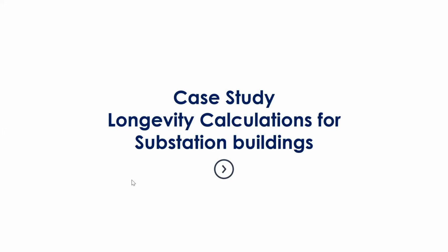BS 449. And in the offshore structures, there are 4 kinds of analyses which are run: pushover analysis, fatigue analysis, in-place analysis, and as a result of these analyses, the decisions are made based on actual condition of the structural members, basically piles and flooding members, whether life could be extended or not. As long as concrete aspects are concerned, which are coming near to jetty, there is also the impact of how effective the CP system is there, what the condition of those particular concrete members is, and then the same 8 factors approach is applied there.